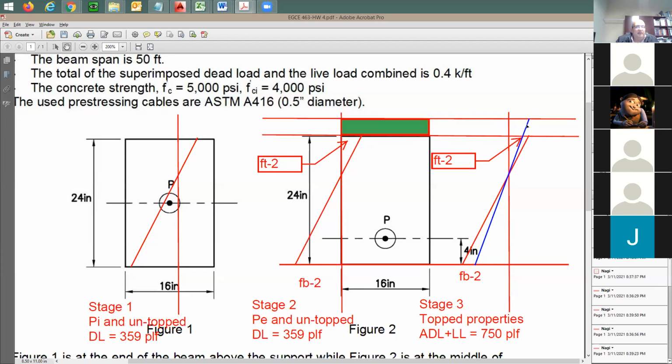So let me take this, and now let me look at the top stresses. The top stresses here are not going to change from this blue pile or blue values, right? It's not going to change. The bottom stress here is going to be equal to the originally developed stress F2 plus the new value. And here is the new value.